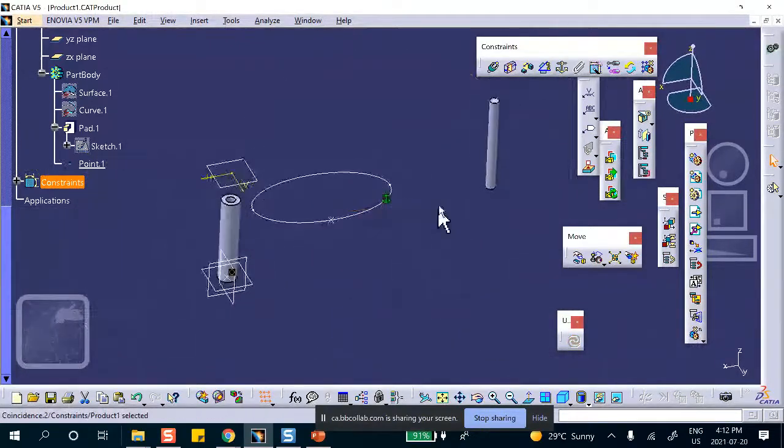Okay. Now I'm going to insert this guy in that guy. And I'll let it go up and down, but I don't want it to spin. Because if it spins, you have an extra degree of freedom that you cannot control. I mean, if you just put axis to axis, it becomes a cylindrical joint. It has one degree of freedom for axial motion and one for rotational motion. Now, I don't want that. I want this thing to be prismatic with that so that it doesn't spin. So we do axis to axis and then plane to plane.